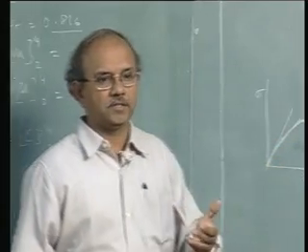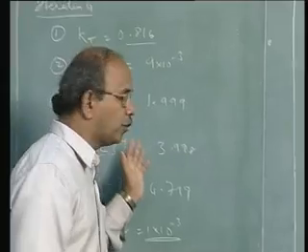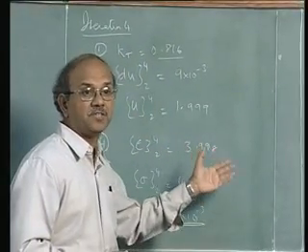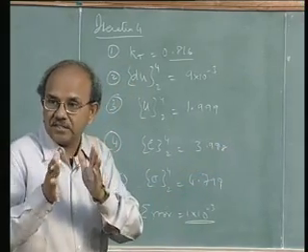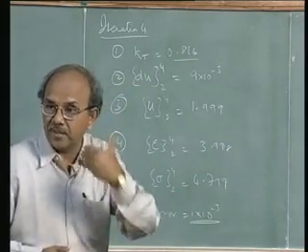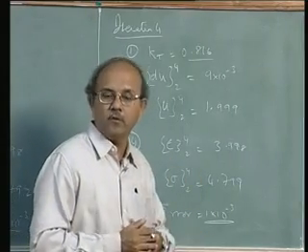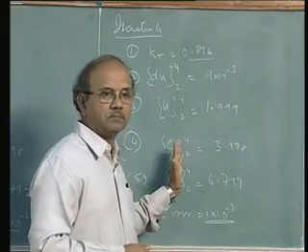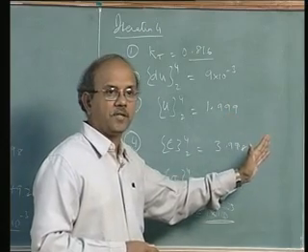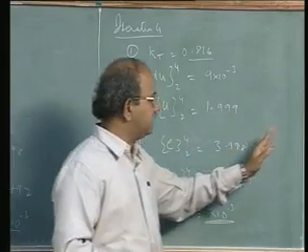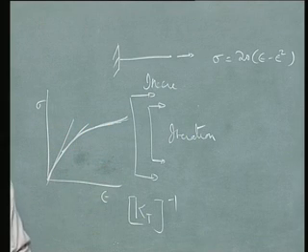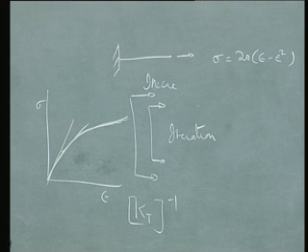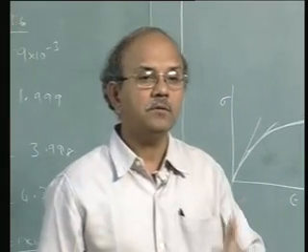Yes, in other words, the error, and hence the number of iterations that are required, depends upon the shape of the curve. Suppose we have taken 4 iterations, and I have the same step, the same size of loading, in the next step. I go to step 3, say I put another 2.4. Will I take more iterations? Of course I will, because as I move towards these positions where the Et happens to be smaller and smaller, my time step or my load step, both being the same, have to reduce.